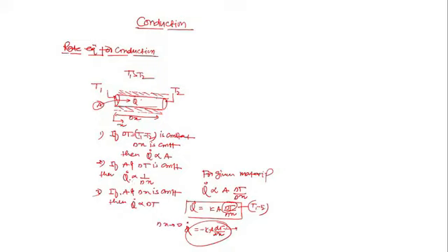And this is the heat transfer in the x direction, Q dot x. As far as flux is concerned, small qx is equal to minus k into dT upon dx. Is this clear, beta? And this minus sign indicates temperature decreases in the increasing x direction. This is Fourier's law.